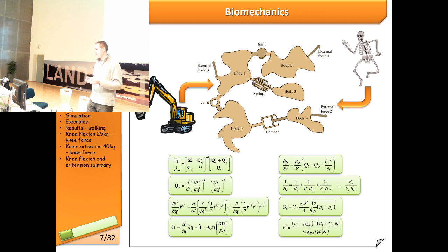with something. So in case of an excavator, you have, let's say, a bucket, an arm, and some other parts, let's say the main structure, and they are connected with revolute joints, so they allow rotation. Plus you have actuators on top of that that move those structures with respect to each other by applying forces. And of course, when the excavator is digging in the soil, the contact force between the bucket and the soil will be transmitted back through the actuators and through the structural elements to the rest of the excavator.